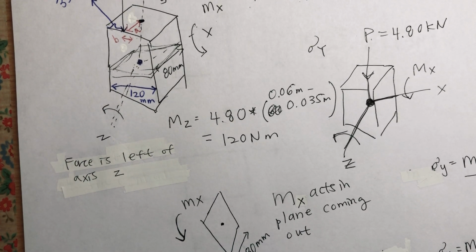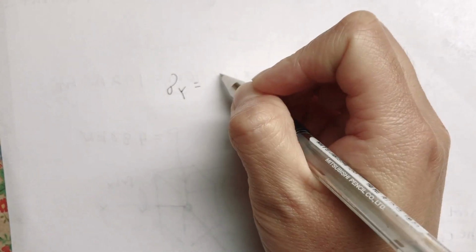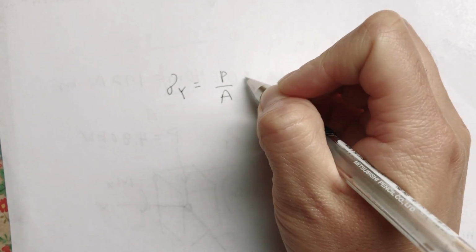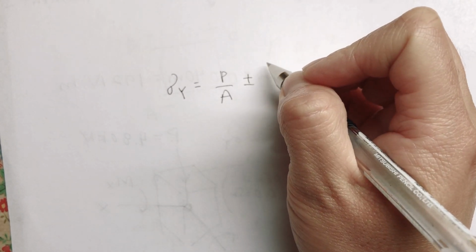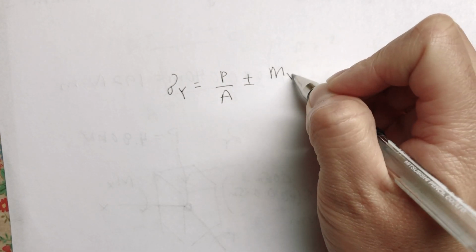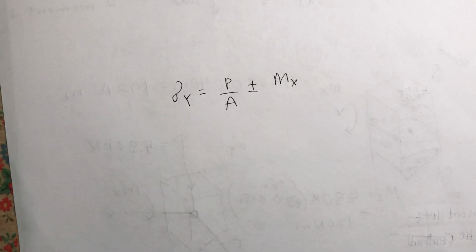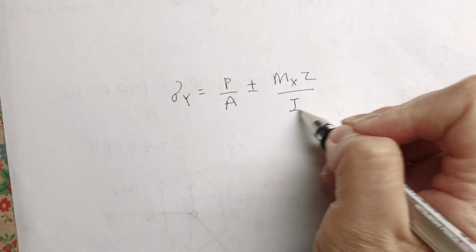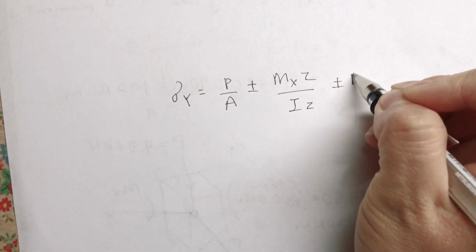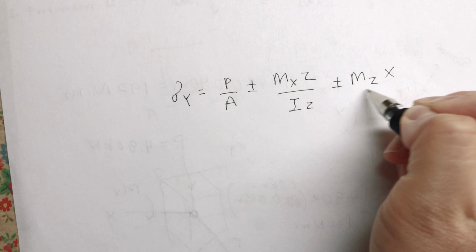So again, the equation that we're looking at is stress y equals centric load plus or minus mx z over Ix plus or minus mz x over Iz.